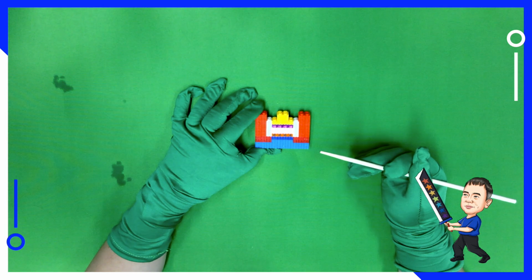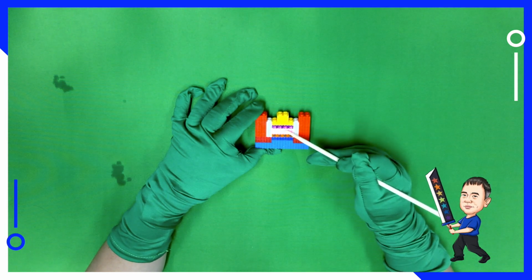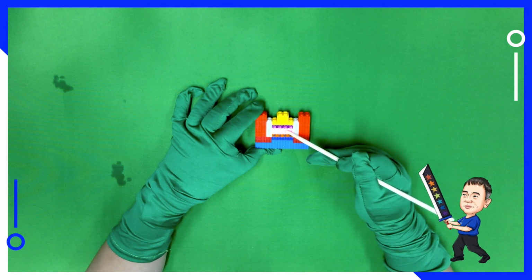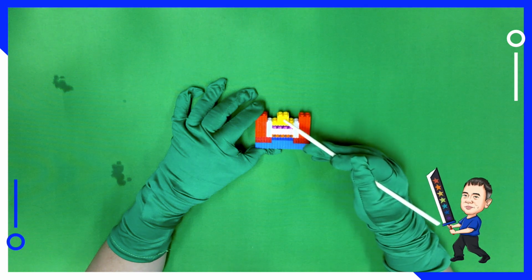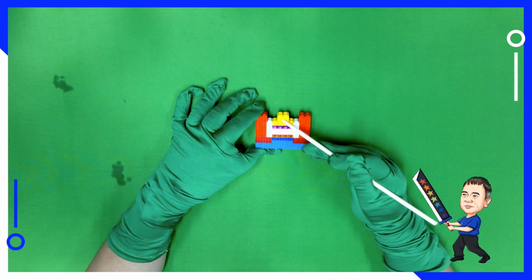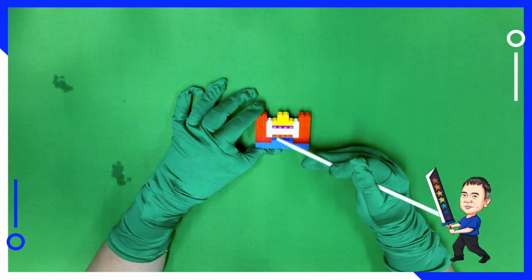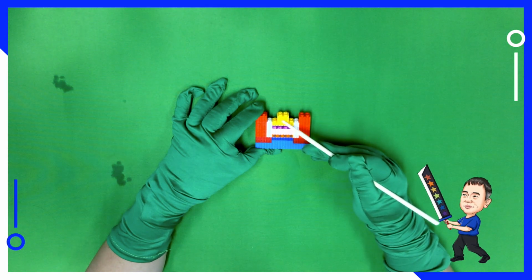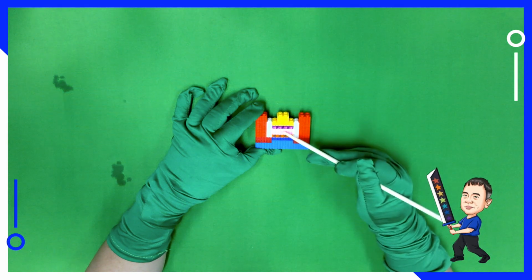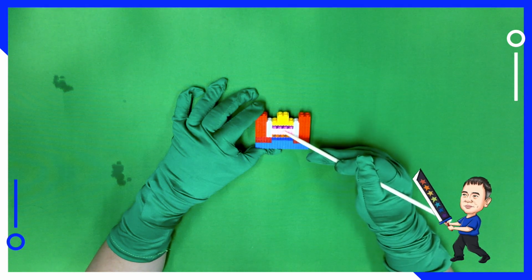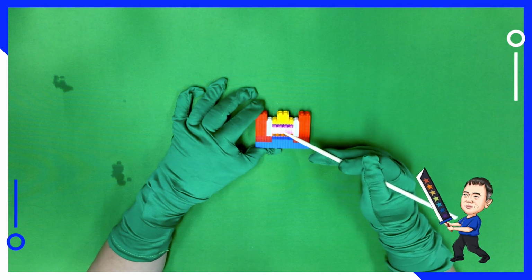And if there is no charge in the floating gate, but I apply a very, very high voltage on the control gate, then the current will flow through no matter whether there's charge or no charge in the floating gate. So two conditions.